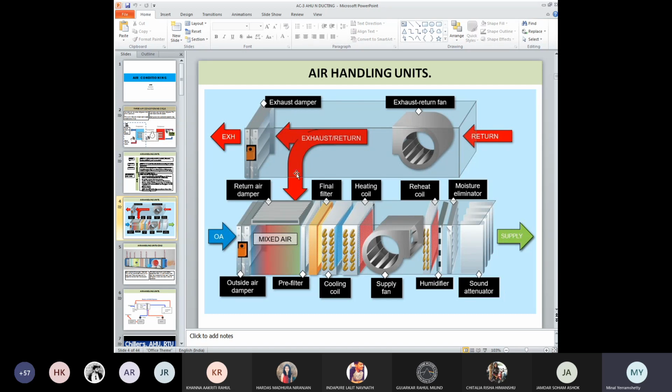Okay, so imagine from here the return air is coming all the way up here. To this return air, you also add the 25% fresh air, right? Because that is outside air. It will have pollution, it will have heat, and all that, but it has oxygen.